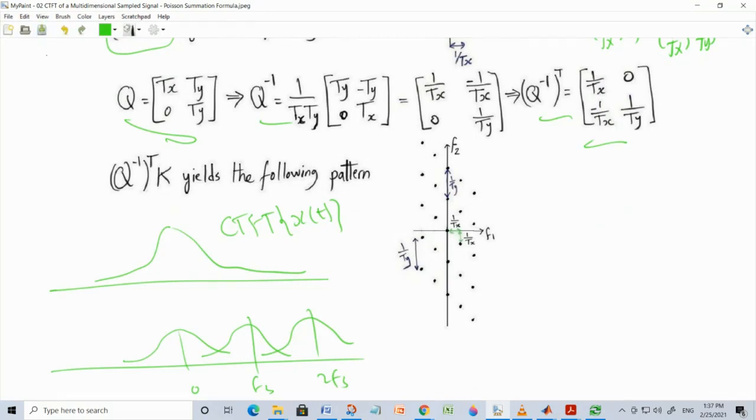So we typically focus on band-limited signals, and band-limited signals are a mathematical fiction. They do not really exist in reality, but we can get very close, and actually we force our signals to be band-limited. In applications, you have a signal, and you can apply a filtering operation, specifically a low-pass filter, so that you force it to be band-limited. But you remove part of the signal, and which part to remove? Well, it depends.